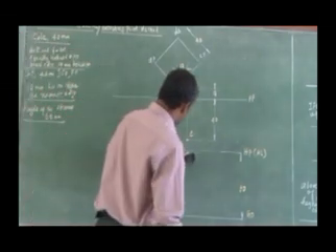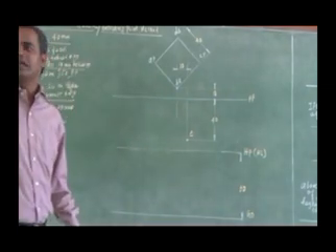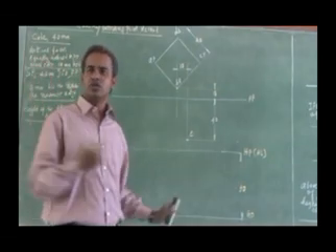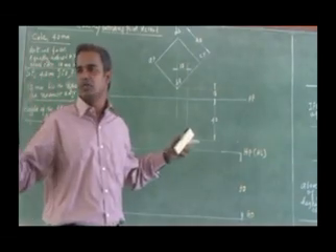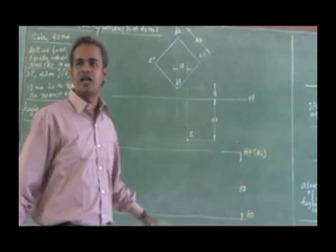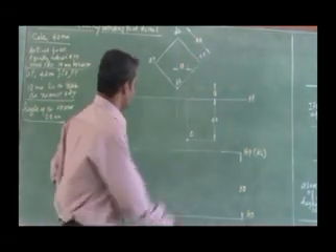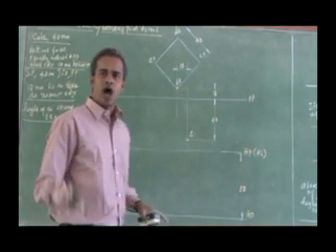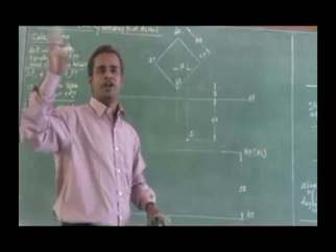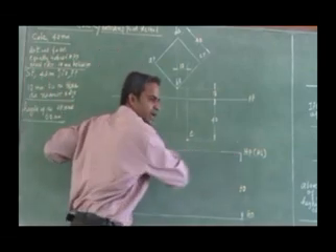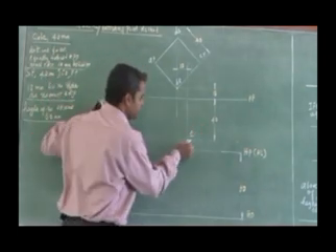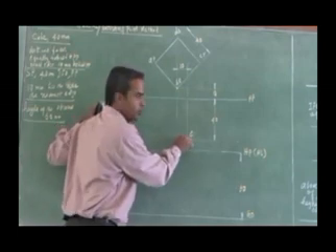Once this is over, listen all of you, not like the previous one, I have to try to get a vanishing point. So this is 2-point perspective, and I have to get 2 vanishing points, a right side vanishing point and a left side vanishing point. How do we obtain the vanishing point from the station point? Always, the vanishing point falls on which plane? Horizontal plane. So I have to get my vanishing point on the horizontal plane. That is for sure.